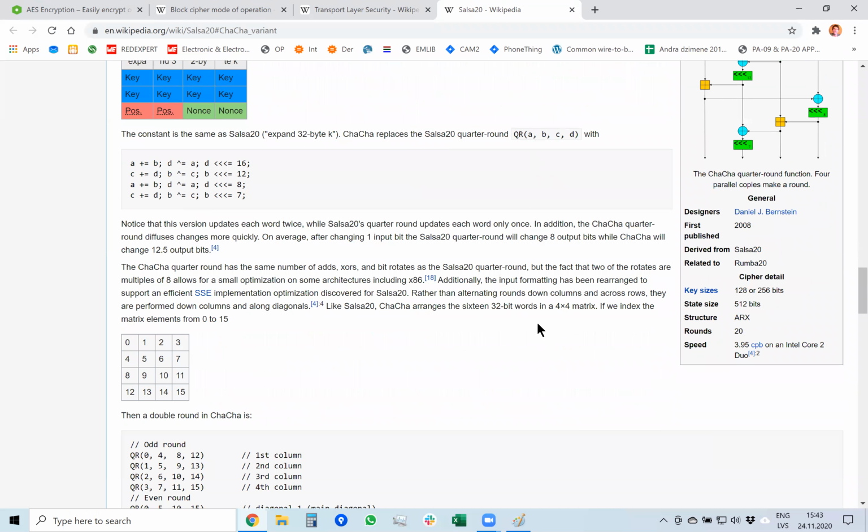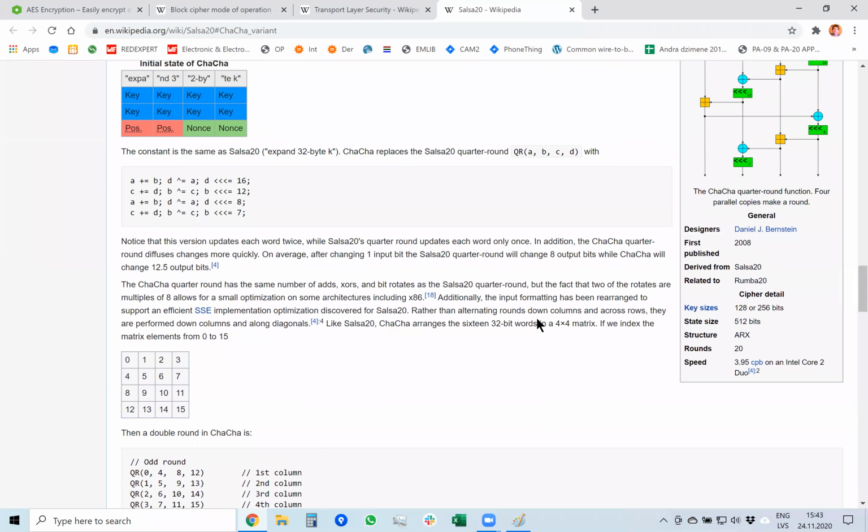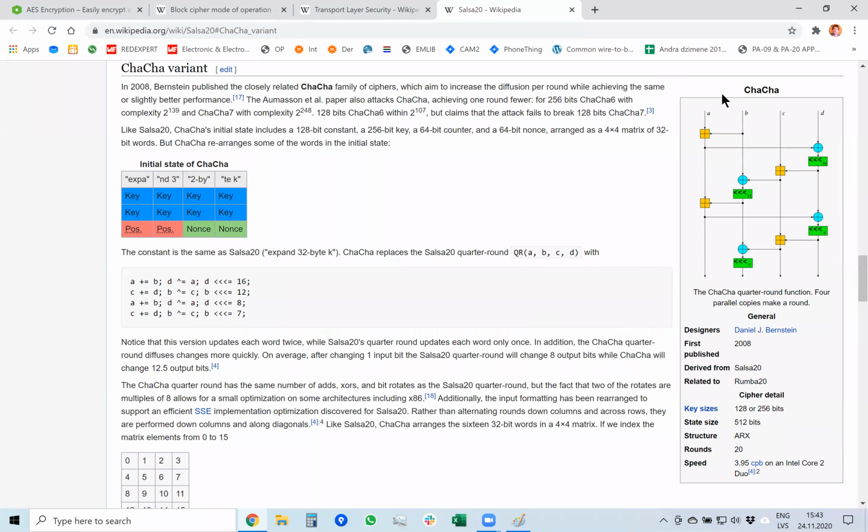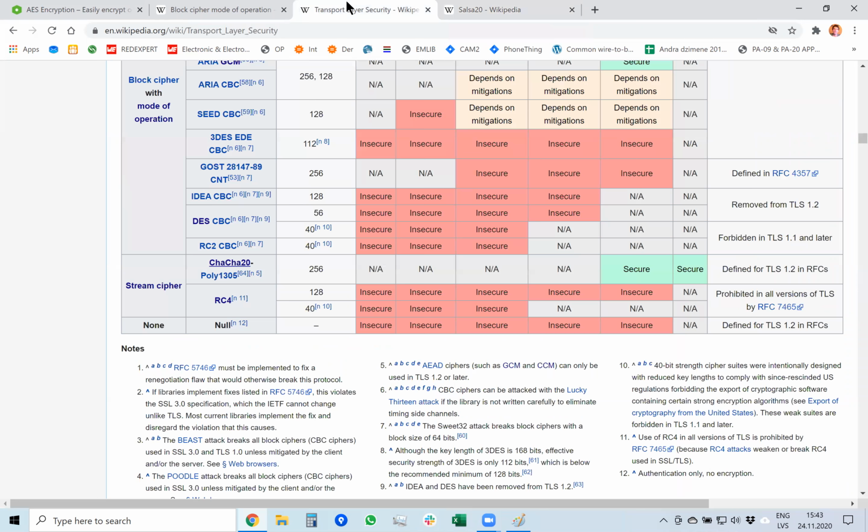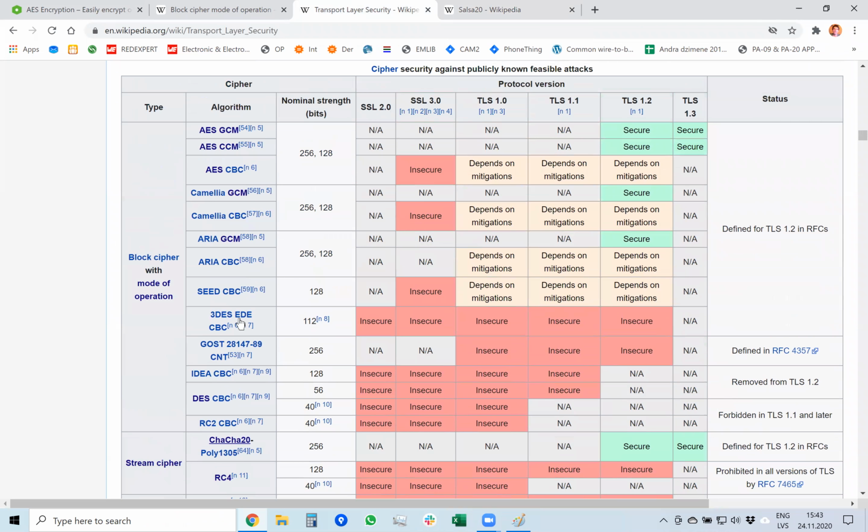And these algorithms exist. But the problem with these algorithms is that most embedded systems don't have them built in. AES is easier to implement, more common, so most people just use AES, and if they only want to send 1 byte, they just have to add 15 zeros at the end and then encrypt and then send. So stream ciphers are not that mainstream. Maybe they are in servers, but in embedded systems, they are not very popular. In embedded systems, everybody uses block ciphers with AES, okay?